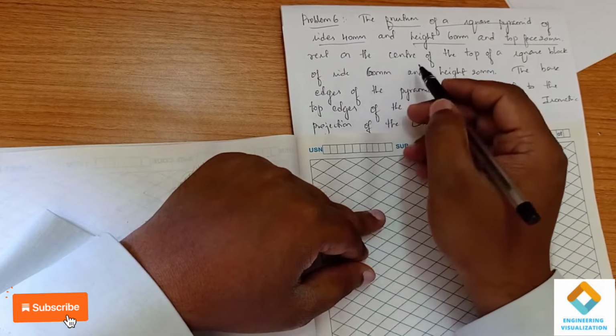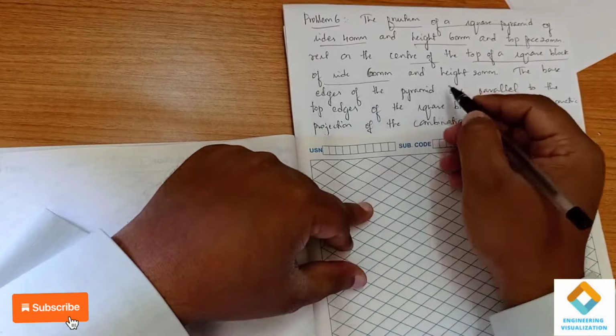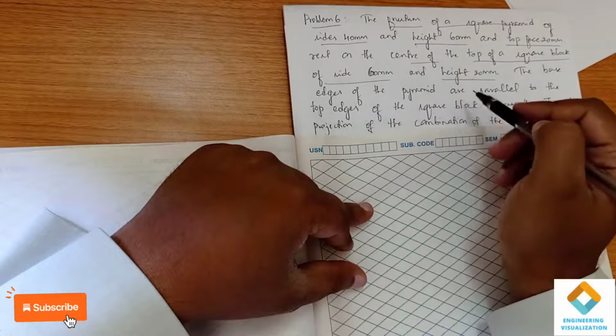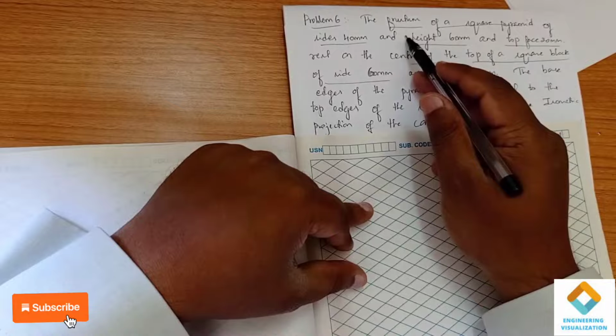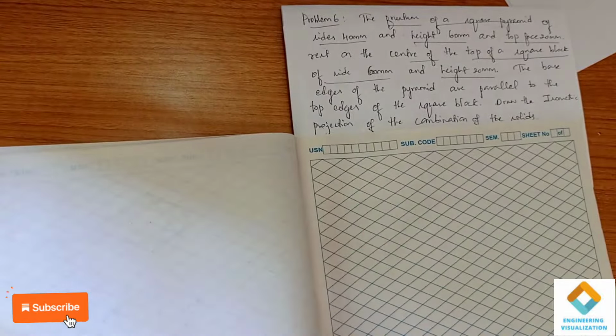It rests on the center of the top of a square block. Okay, square block of side 60 and height 20. So first we need to construct a square block of 60 and height 20. Above it we have to place a frustum of the square pyramid. Okay, so first I'm going to construct a square block.